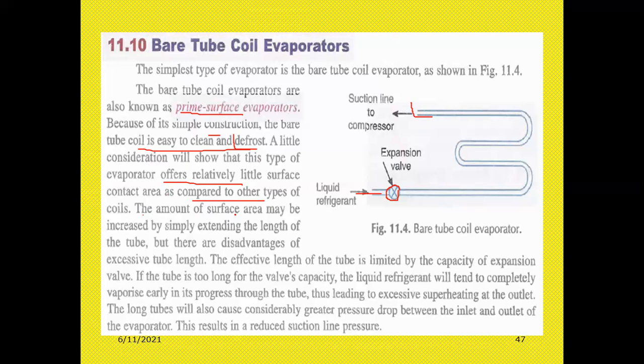The surface area can be increased, depending upon the length of the tube, but there are disadvantages of excessive tube length. The effective length of the tube is limited by the capacity of the expansion valve.